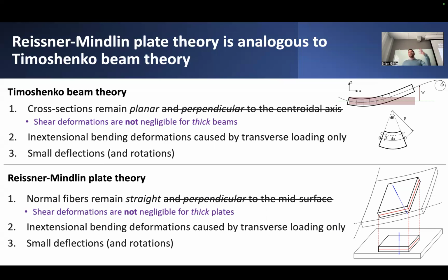And you'll notice if you use these different assumptions in the context of a finite element code, they might say whether a particular beam or plate idealization uses one of these two different notions of beam theory or plate theory, Euler-Bernoulli beam theory or Timoshenko beam theory. And it all boils down to this: is it neglecting shear deformations or is it including shear deformations? Is it allowing the cross-section to deform relative to the neutral axis, or is it maintaining a perpendicular orientation? So that's really the fundamental distinction.